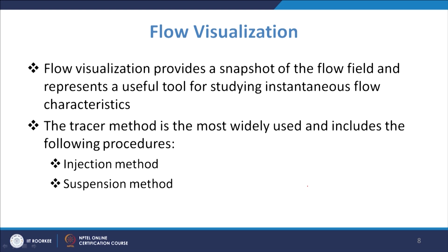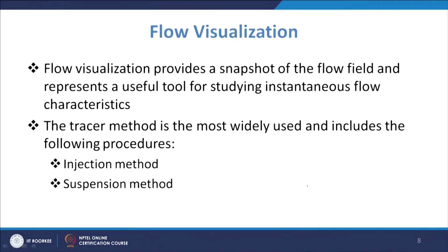What we normally do is make the tundish model or the ladle model using a transparent perspex sheet, so that you can visualize the flow. And normally we put in a tracer. The tracer method is most widely used, and for that there are different procedures.